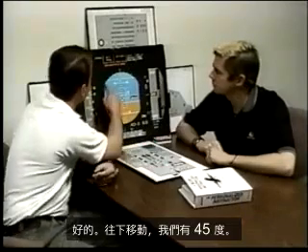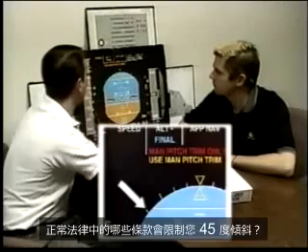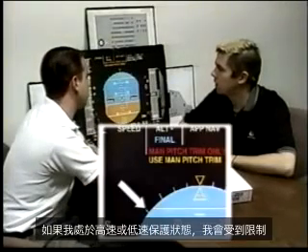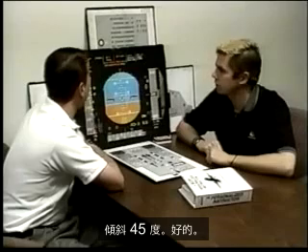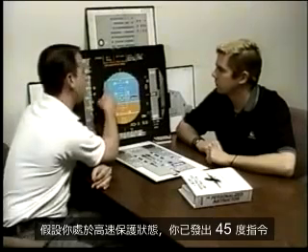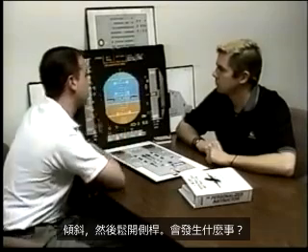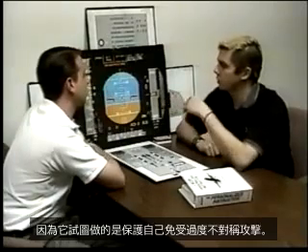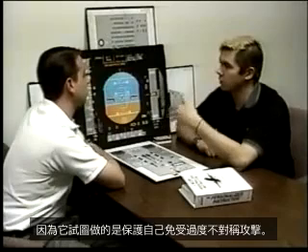Okay, moving down, we have 45 degrees. What are some items in normal law that would limit you to 45 degrees bank? If I were in high speed or in low speed protection, I'm limited to 45 degrees bank. Let's assume that you're in high speed protection, you've commanded 45 degrees bank, and you let go of the side stick. What occurs? If I let go of the side stick, the aircraft is going to roll back to 0 because it's trying to protect itself from over-G'ing asymmetrically.